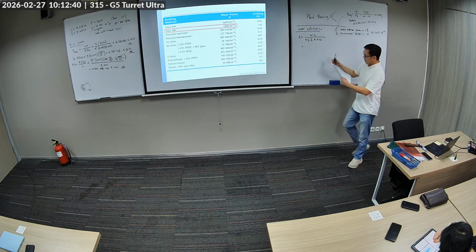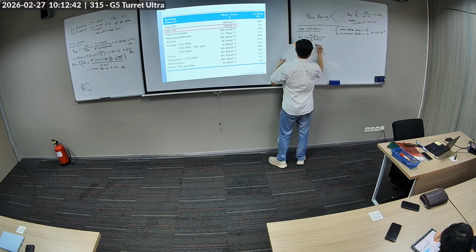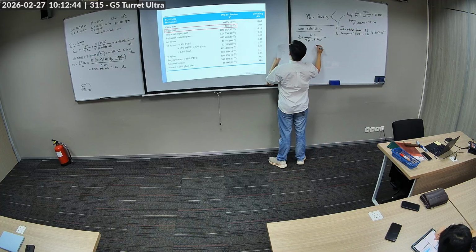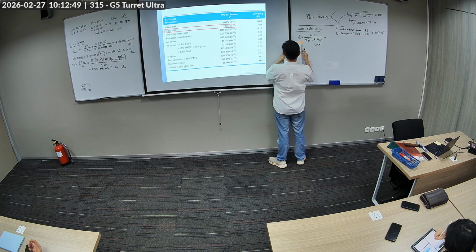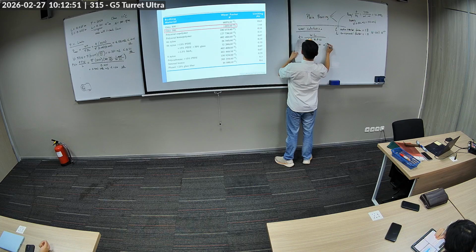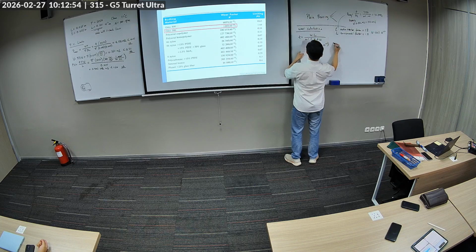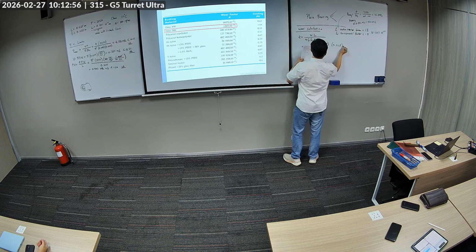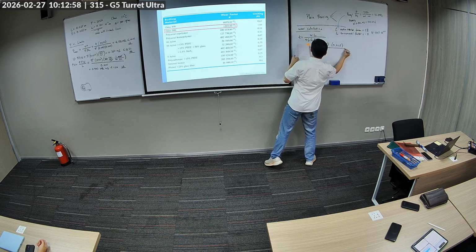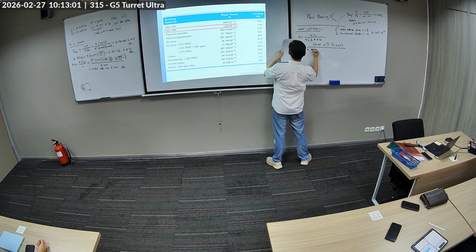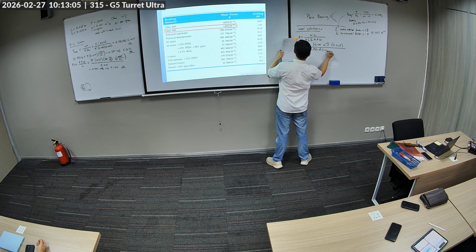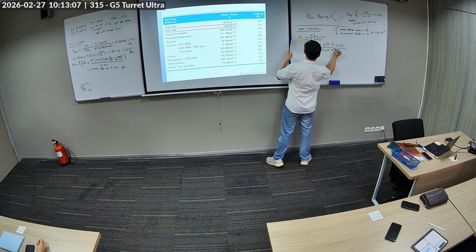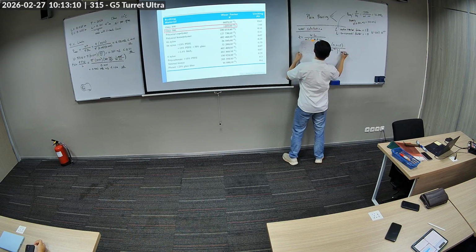Okay, let's go. We have all the numbers. The wear limit W is 10 to the negative 3 in length, divided by 4 times 1.8 times 1.0 times 1207 times 10 to the negative 20. Just do everything in SI units, guys.